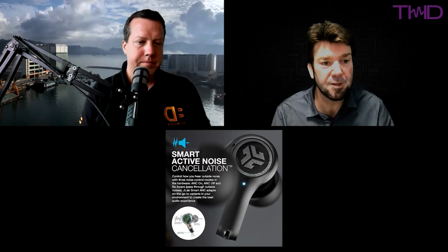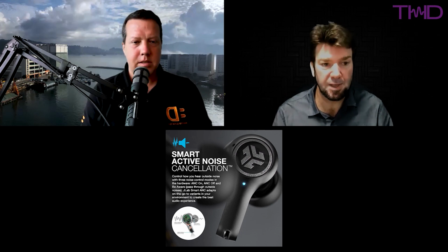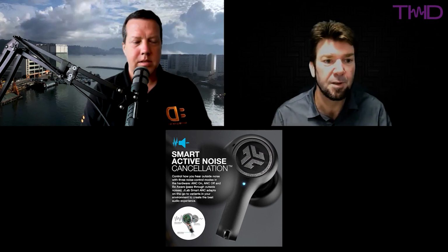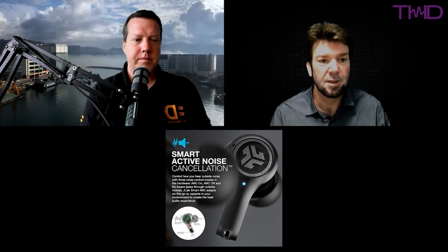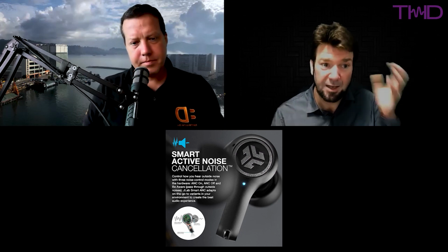Yeah, so pass-through, you just mentioned pass-through. Pass-through is essentially feed-forward in reverse. So instead of cancelling the noise, you're going to compensate for the shielding effect of the headphone, and drive a frequency response. So again, in principle, you could recreate the perfect sound as though you had no headphone on. Right, would it use that mic on the outside to pick up? You use the same mic, yeah. You just change the filter. All you do is change the filter that microphone signal passes through, so that when it arrives at the eardrum and mixes with whatever sound has come through the headphone, it sounds exactly like you had no headphone on.